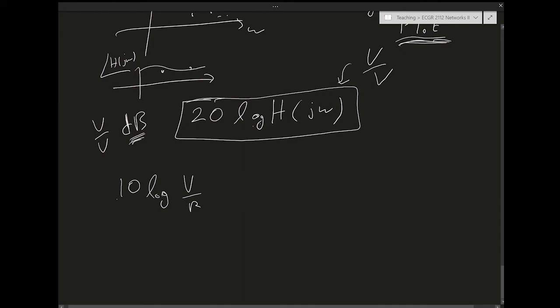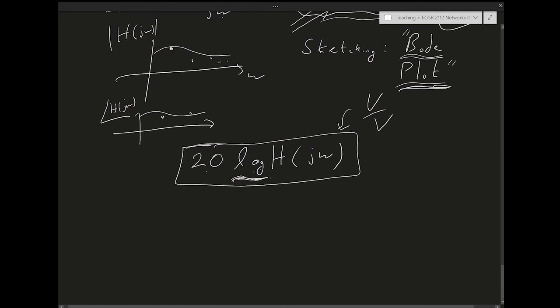And this is what gives the 20. So for all signals in electrical circuits, to get to the dB formalism, we find the log and then multiply by 20. Whatever the reasoning is, the key thing is that it's the log function that simplifies things. The 20 doesn't do anything, it's just a constant that is there for a historical reason.